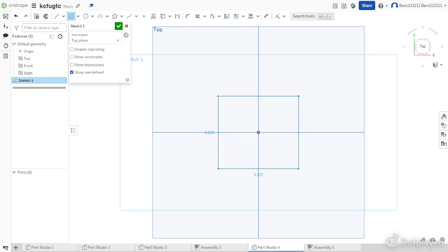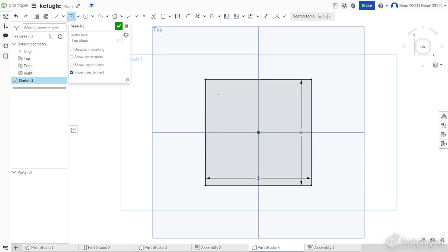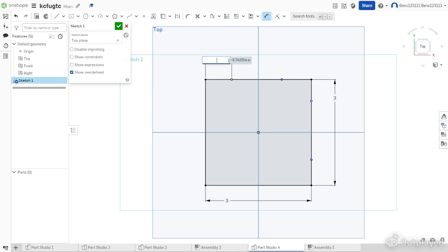When you're using a center point rectangle at the origin, it's going to be centered at the very center of the sketch. Now what I recommend is drawing out your dimensions so they're not cluttered up. Then from here you want to take 2 points, put them on the top edge and the right edge. Then take your dimensions and make sure that the point closest to the left edge is tied to this corner. You want to have a dimension of 1. Repeat that for all the other points.